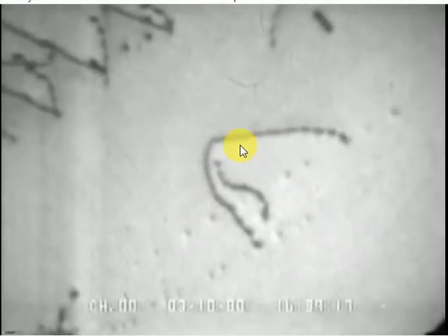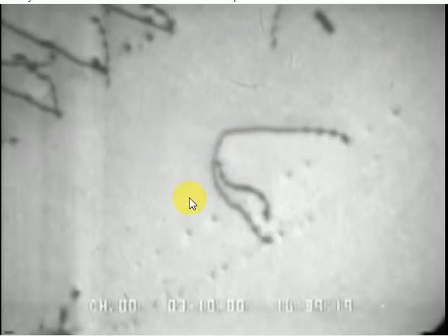And this is an example of how a dislocation may form during deformation. As you can see, the dislocation forms here, and then when the stress level is increased, the dislocation moves from this direction in this particular direction. These are the new dislocations which are being generated from this place. And here there are many dislocations which are pinned for certain reasons. So once again, the movement of dislocation is hindered here.